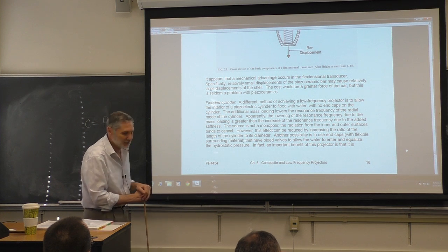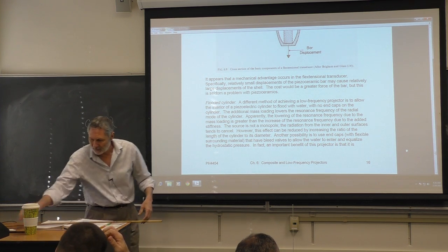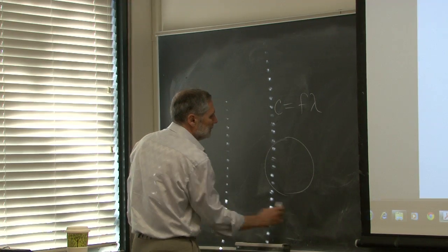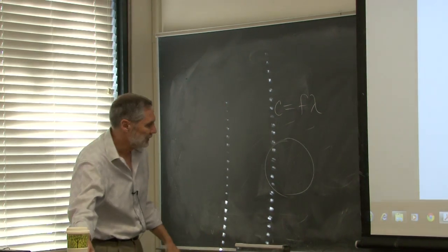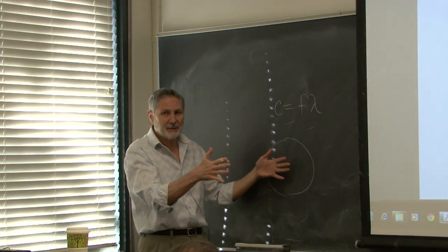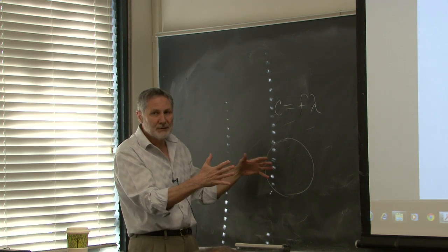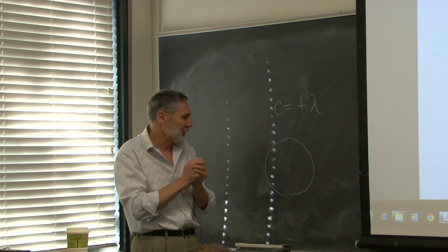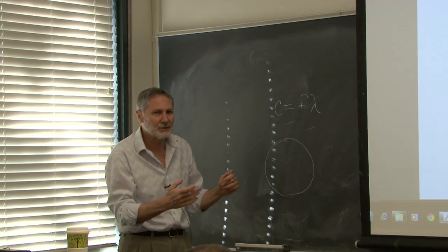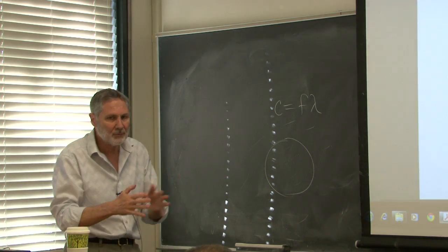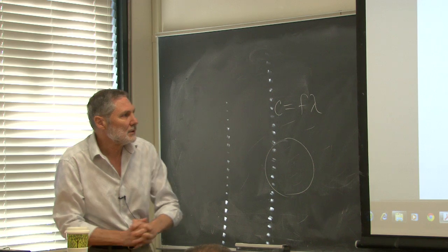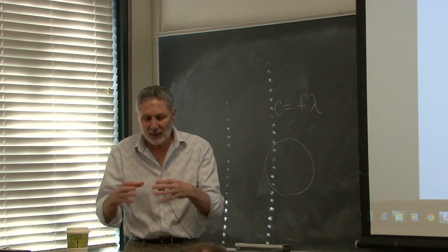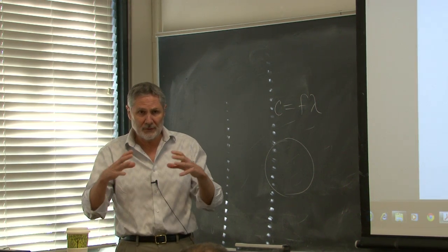Now this is interesting. If you imagine you have a cylinder here, and you flooded it in order to lower the frequency, what happens out here? Well, if it's open, now you're back to this dipole source kind of thing, or actually quadrupole or octopole, I don't know what it is here, but you don't have a monopole source, okay? So you would want to somehow cap off the ends, with some kind of flexible material. And then what happens when you go down deeper and there's greater pressure?